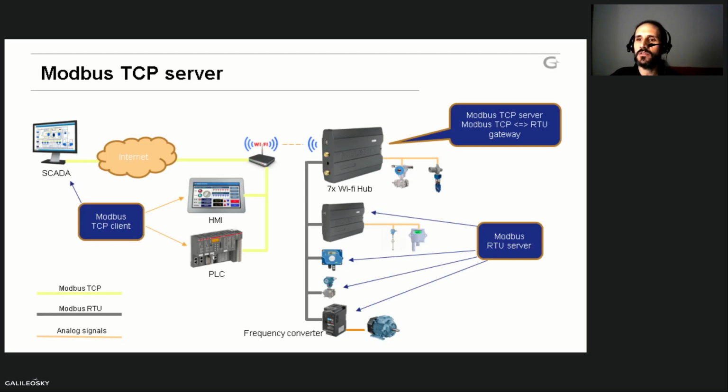So it would work as a Modbus TCP server, but not only that, it would work as an RTU gateway. It can get data from the RTU bus and show it to TCP clients. And that's the main idea of this new feature that we are presenting today.